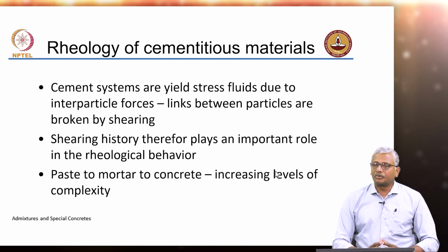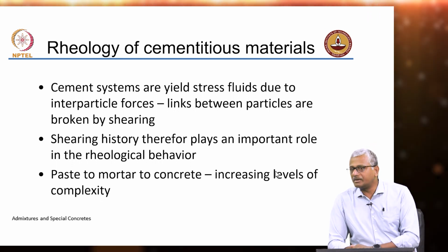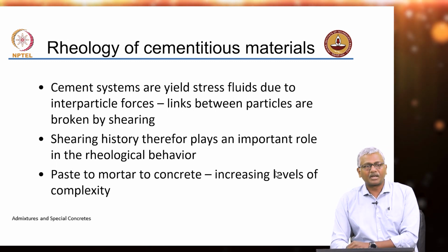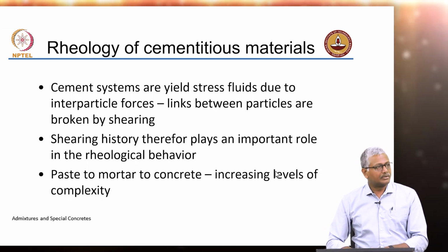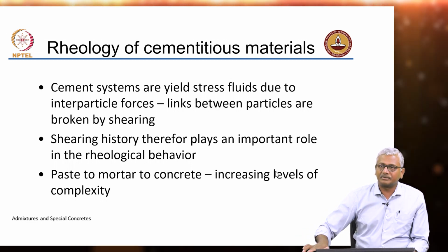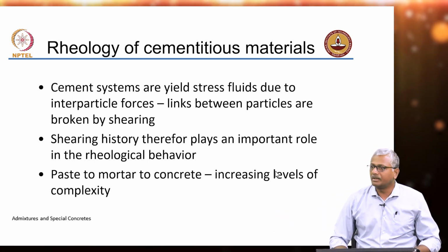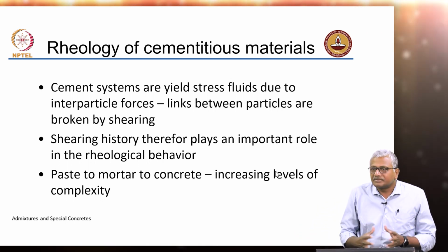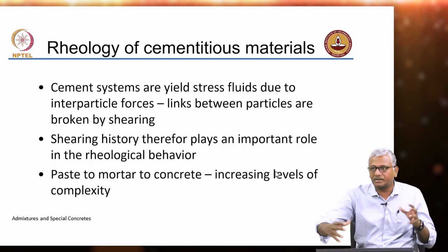Now, if you remember your basic understanding of water and oil that you learnt in your science textbooks, water and oil have viscosity, right. But as soon as you apply any shear, water will flow, okay. So, if you have a pool of water on the table, for instance, if I simply press that pool of water, it starts flowing. Concrete on the other hand, let's say you dump some concrete on this table, if I just press it, probably it may not be sufficient to cause it to flow. I may need to agitate a little bit to cause it to start flowing out.